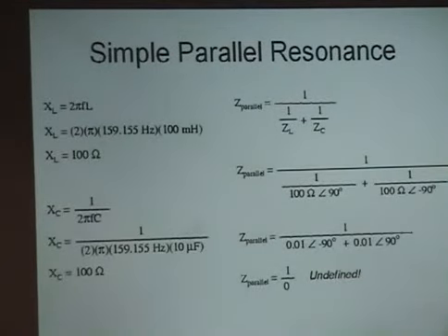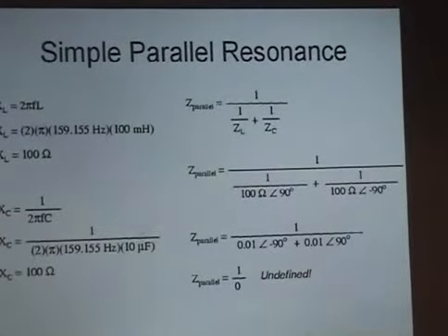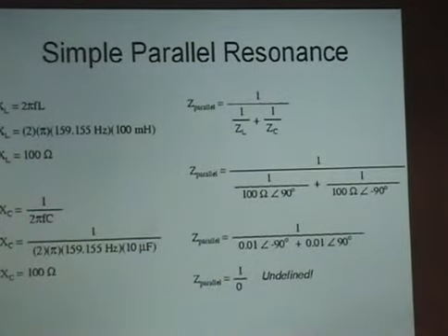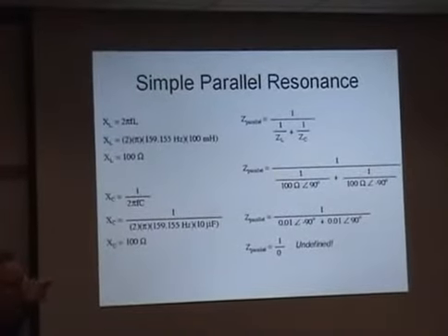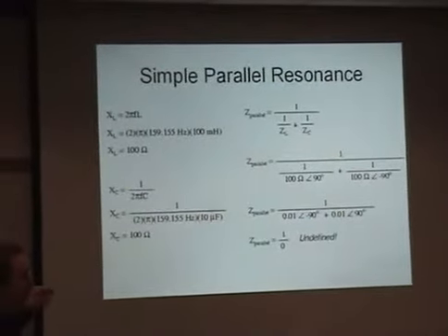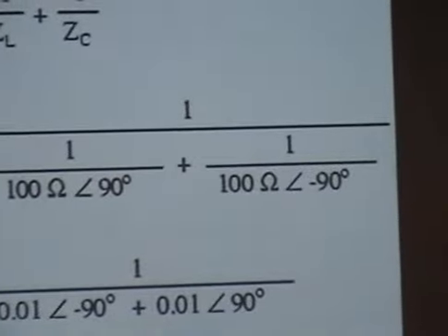But what happens here is you look at the reactances and you put them into the E equals IR or E equals IZ format, and you put them together like they're in parallel, like they were in the circuit. Same thing as in resistance, 1 over one resistance, 1 over the other resistance, you add the inverse. Well, all of a sudden you see minus 90 degrees, plus 90 degrees. Oh, what happens here? We add those together and we get 0. Well, that's what happens at resonance.